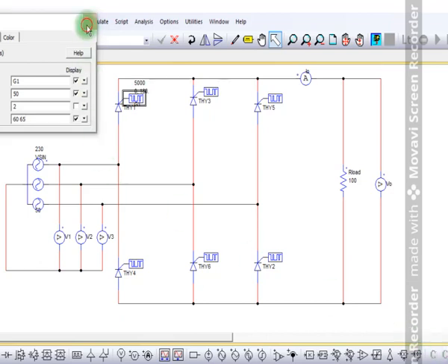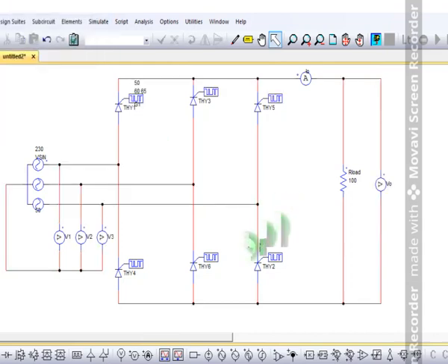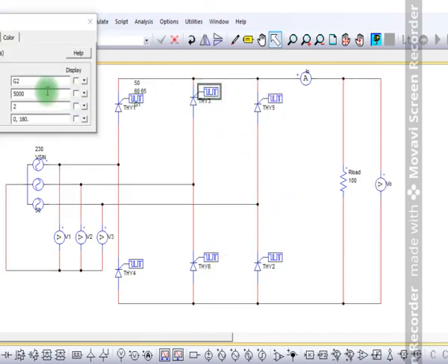Then we'll substitute the values for G2. The frequency is 50 Hz, and the switching sequences are 120 to 125. Then the next is thyristor 3. You put 50 Hz and the gate is G3, and the sequence for the third thyristor is 180 to 185.